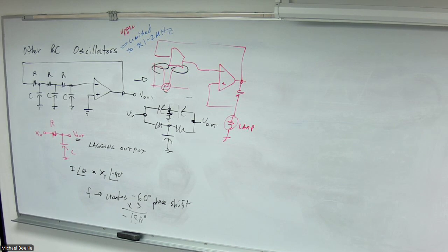You don't need to change either R or C, you don't need to. Correct. Yeah. In fact, for example, for the function generators that you built for your trainer, what they do is the capacitors are changed by the switch. And so you have capacitors that change by a factor of 10, and then you use a variable resistor to change R, and that gives you the fine tuning. So you're changing both.